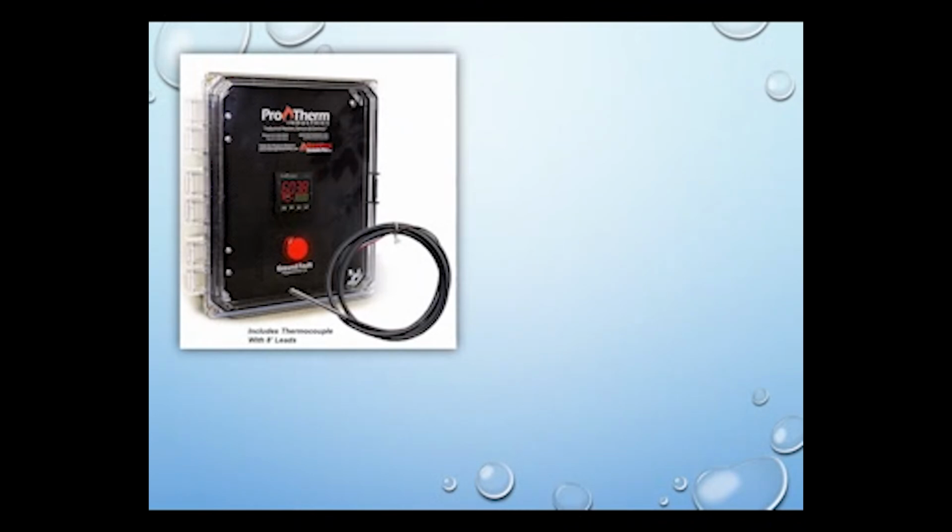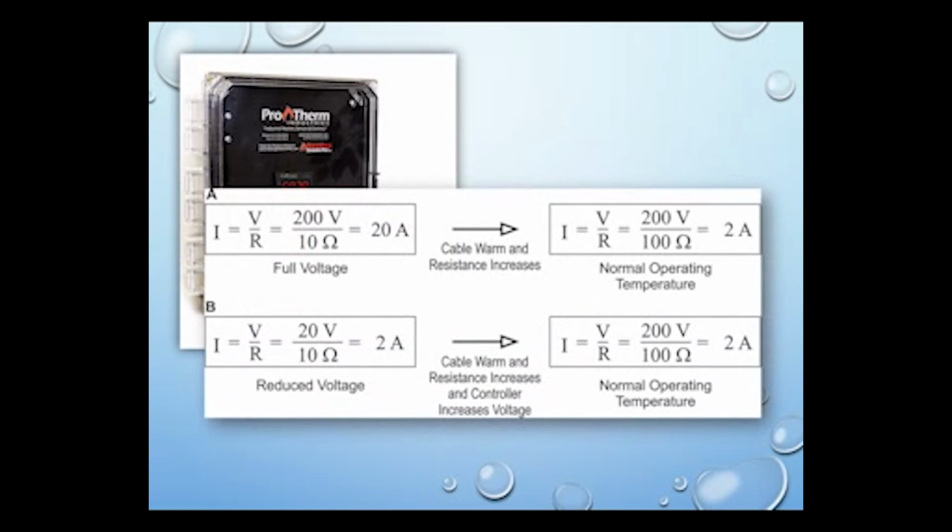Often we can use electronic controls which utilize solid state components that give us faster and more reliable control than using contactors. They can also provide us with a soft start, which would prevent nuisance tripping of heating circuits because the initial startup of the self-regulating cables can cause high initial current flow since they have low initial resistance. The electronic controller gradually increases the voltage to the system to prevent that rapid current rise. The voltage increases as the resistance increases as the cable heats up.